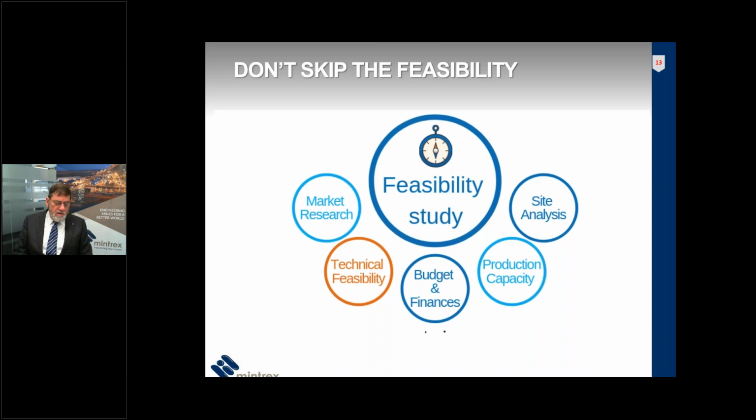So don't skip the feasibility. It provides an opportunity to explore the project planning in detail, including pioneer work and other works which are going to be very site dependent. It should prepare the ground for a successful project by presenting a comprehensive project implementation plan. The various stages of feasibility should progressively flesh out the plan, including the identification of the early works, and ensure an efficient and orderly progress of site mobilisation and groundbreaking works. And also will consider things like local social issues, the environment, weather. All those things are important.